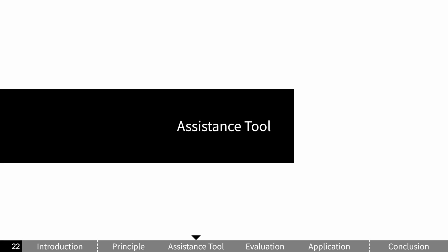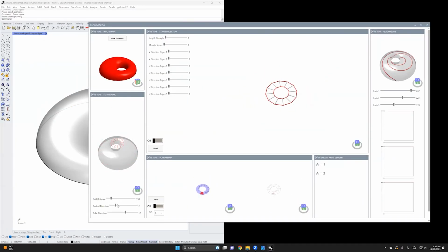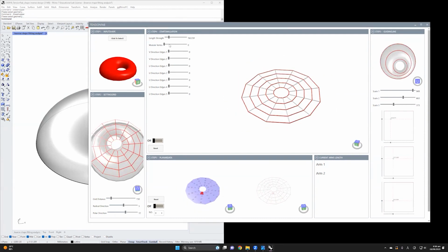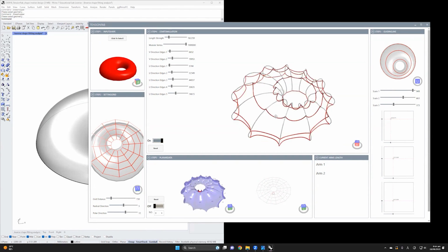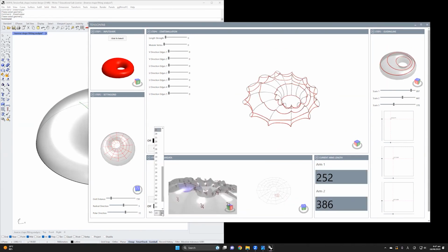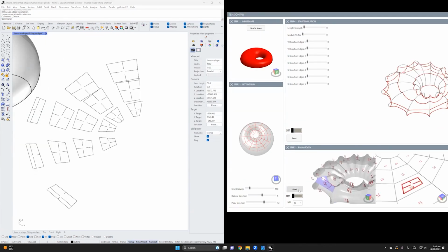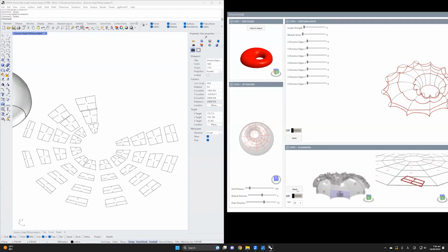We developed 2 interactive design assistant tools based on Grasshopper plugin in Rhinoceros. The second tool assists users in conducting tessellation simulation on a given target surface, optimizing the shape of the modules, and calculating the position and length of the arms in the planar state. Ultimately, the 2D baselines can be exported to the Rhino view for the next step of creating processing data.